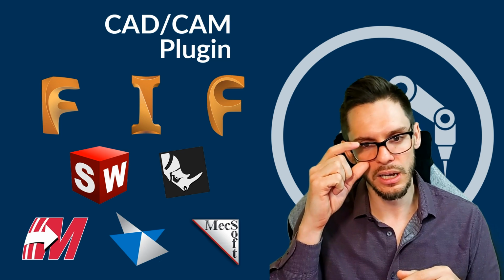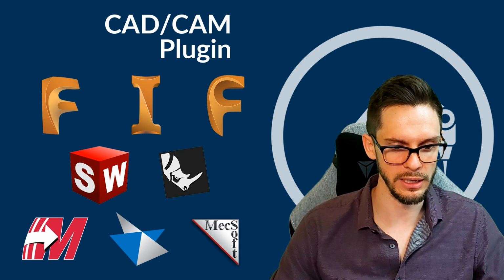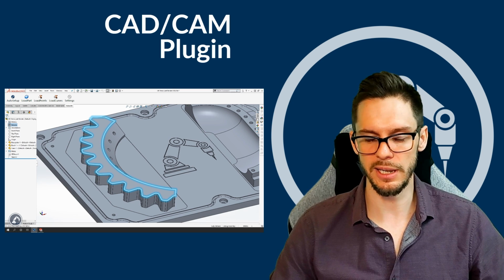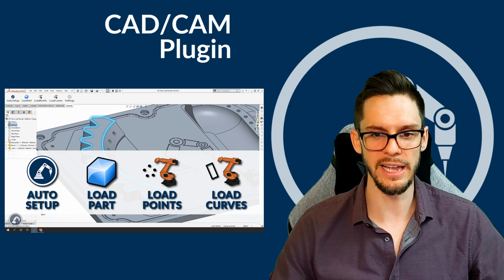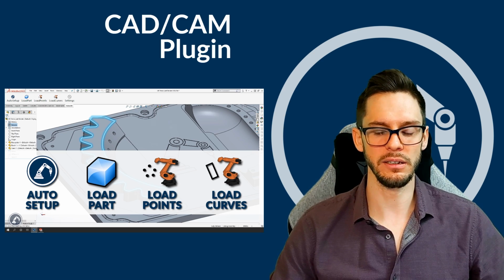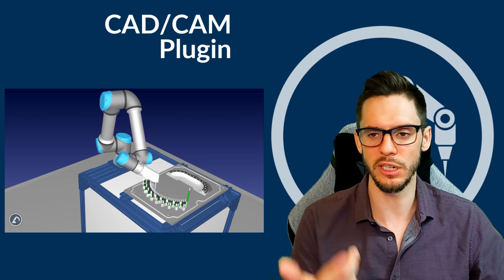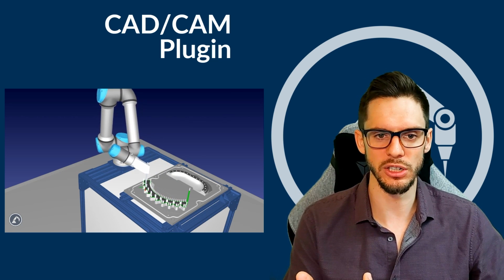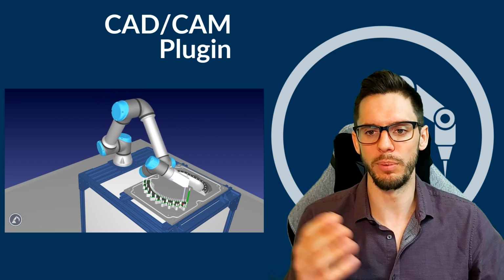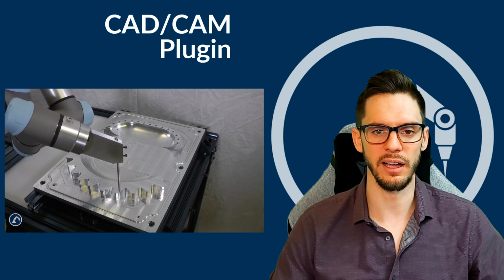So this is great. Here's a small example of how it works. If you have the part, you can select whatever feature you want to import, in this case an edge, but as I said before, it can be the part, points, or the curve. Then you import that to RoboDK. You can then manage the tool orientation, approach and retract movements, IO activation, and other parameters. Then you generate the path and upload it directly on the robot controller to be executed just like this.